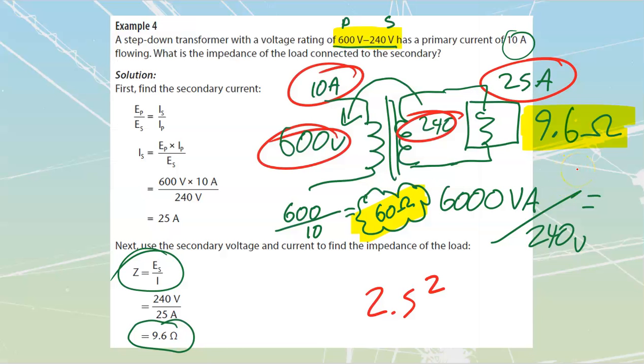We're not going to work with that, okay? You should see that there is a relationship. It is all mathematical. If you go through and expand out your Watt's law and your Ohm's law, you will be able to prove this squared ratio relationship. What I want you to pull out of what we have just done here, though, is the fact that there is a relationship to my impedance across from one side to the other, and that my transformer doesn't change the impedance, but it changes what my source sees. My source sees this 9.6 as a 60 ohm impedance over here.